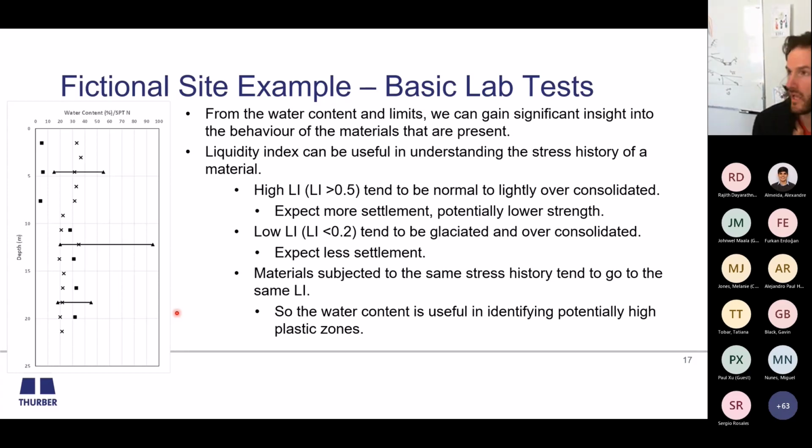where we expect to see movement. And I think, for example, there's a dike there. It was originally designed 4-to-1 side slopes, and due to movement on these high plastic layers, I think it's 25-to-1 side slopes. So it's that was one of these things that they found through pain. So they had built this original design, and then it started moving, and they had to keep buttressing this to support and stabilize the structure. But now through their pain, we've got this, okay, we have to be cognizant of this high plastic layer.